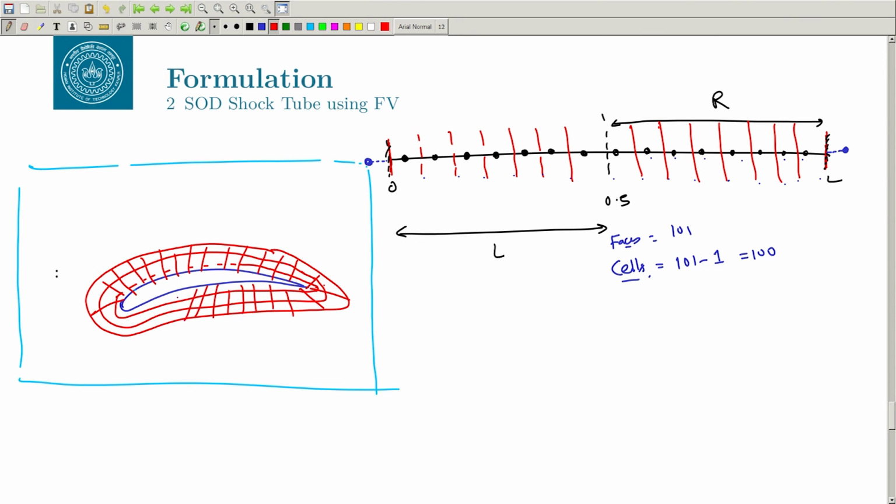In 2D it is very nice quadrilaterals, but you have to match to the outer boundary. So, what you can do is have a grid which is just growing, matching the boundary, any kind of grid. You can have an unstructured grid completely outside. The only thing that you need to take care of is that you cannot have overlapping elements. Similarly, here you can do whatever you want and go to your boundary, and you can fill this in the entire domain, right.